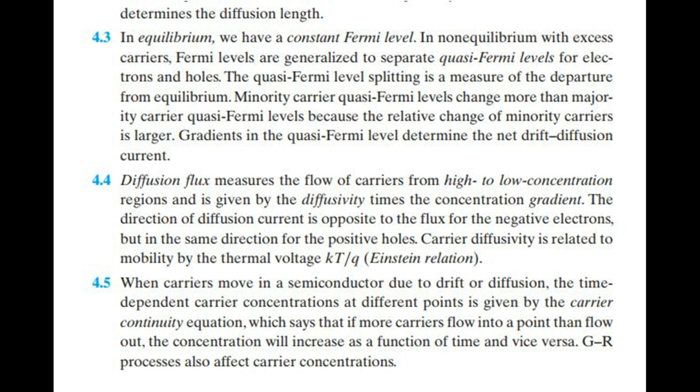Diffusion flux measures the flow of carriers from high to low concentration regions and is given by the diffusivity times the concentration gradient. The direction of diffusion current is opposite to the flux for the negative electrons, but in the same direction for the positive holes. Carrier diffusivity is related to mobility by the thermal voltage, the Einstein relation.